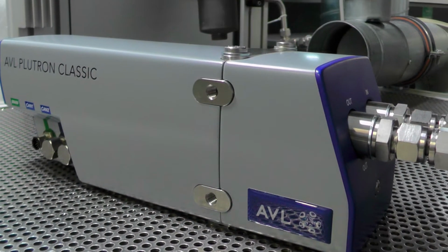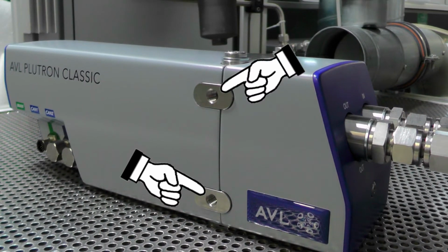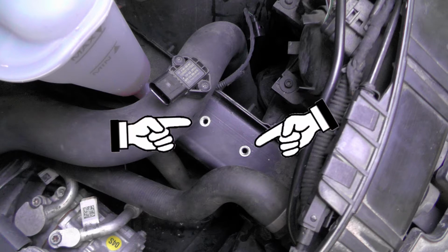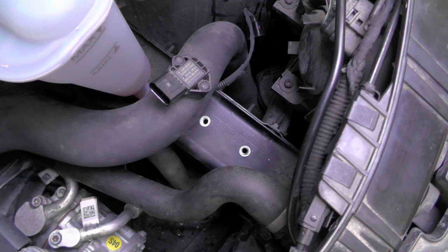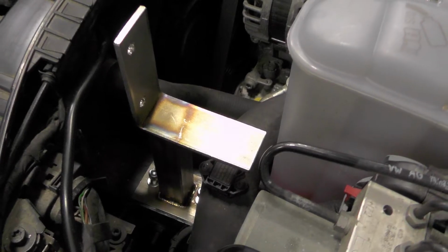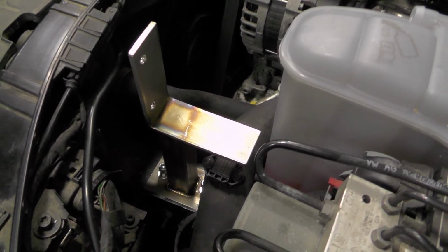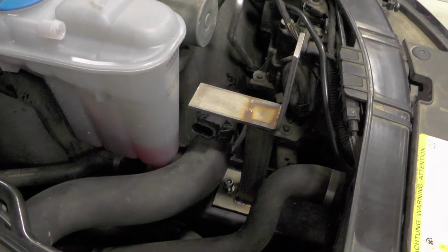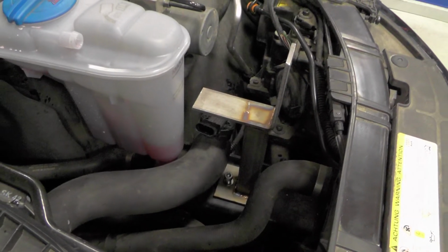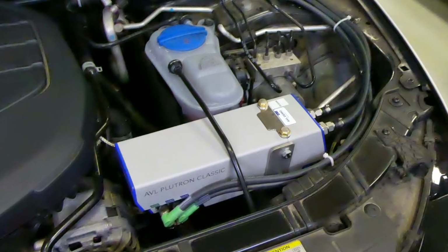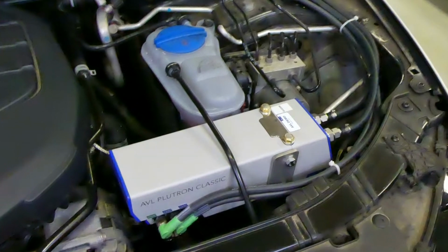The AVL flow meter has two 8mm metric mounting threads on each side and on the bottom where a fixture can be mounted. An appropriate counterpart for mounting the fixture to the chassis has to be identified, preferably close to the flow meter position. The fixture itself can be made from 3 or 4mm sheet metal strips which have to be bent and maybe welded to fit in the flow meter in the intended position. Make sure to leave some extra room for cables and hoses on the sides and in forward direction.